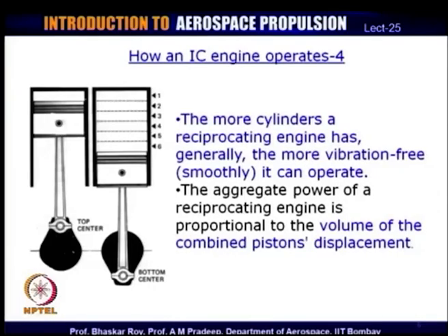If you can create an engine that is vibration free, because what happens is, as we have seen, you have 4 strokes, one of them is a power stroke, and during the other strokes the engine has to sustain itself in its motion, and as a result of which it is possible that there is an uneven application of force or moment on the crankshaft.